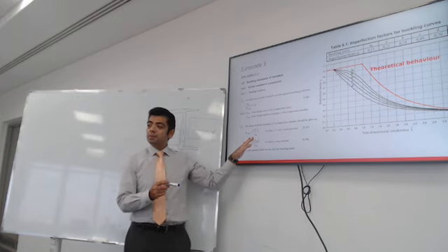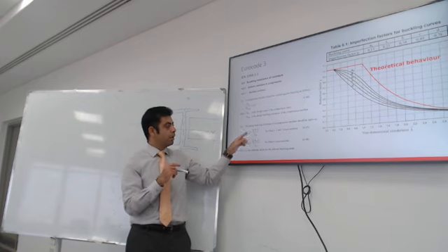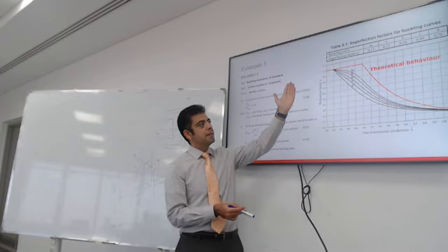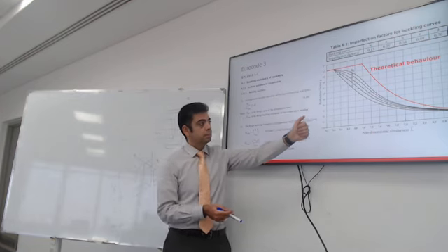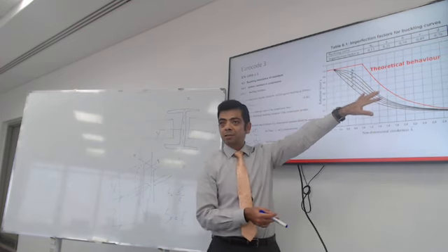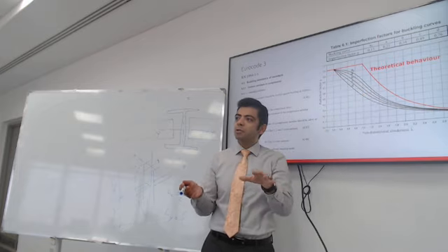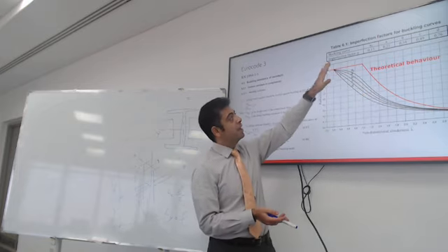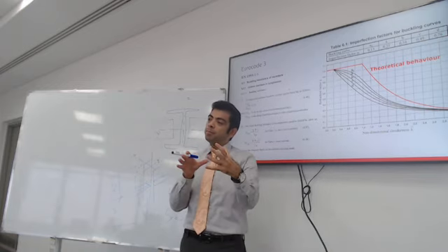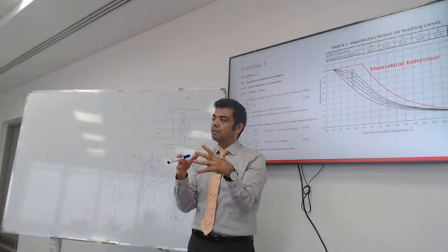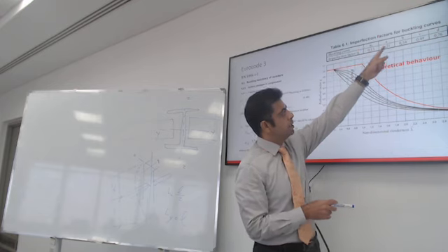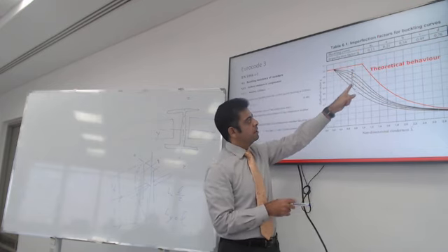This equation is very similar to the equation before, but it has this factor. This is a reduction factor that comes from the buckling curves. The buckling curves are smaller than the theoretical behavior, and we talked about why: because actual life is not perfect. And the table above gives you the imperfection factor. So each shape, depending on the geometry of the cross section, you can pick the buckling curve. There are buckling curves from A to D.